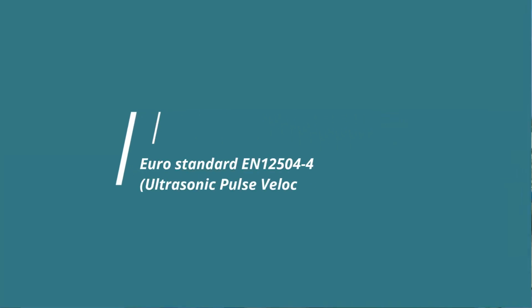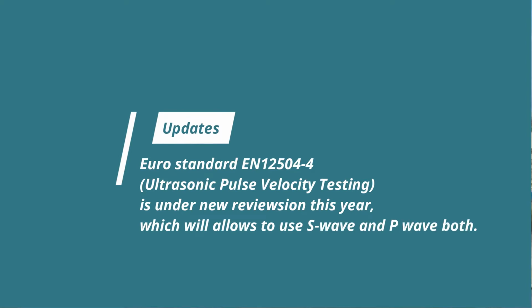Last input from my side on strength testing, where Logesh mentioned before, this EN 12504-4. That's actually the standard for pulse velocity testing, European standard. That's currently under revision. It was due to be released this year. It's difficult to know actually right now with the current situation with the coronavirus, how that's going ahead, but we had a review meeting in January.